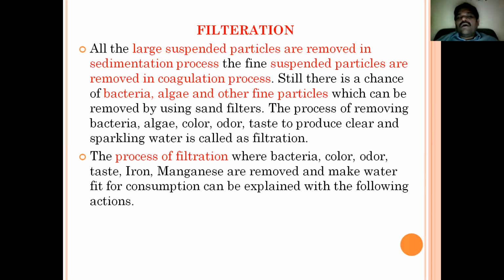Understand? How we can remove this bacteria, algae, and any other leftover fine particles from the water, we will discuss. See here, the process by which we can remove them is called filtration. That is why I mentioned the process of filtration, where bacteria, color, odor, taste, and other impurities like excess iron, manganese, and any other impurities will be removed.